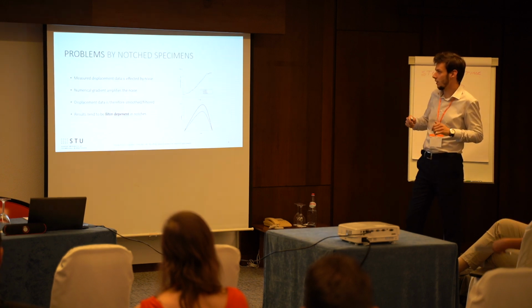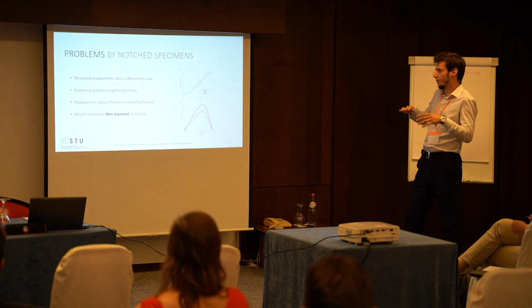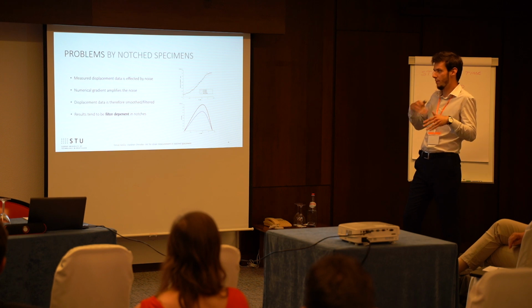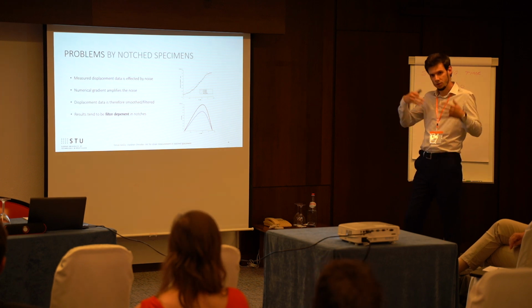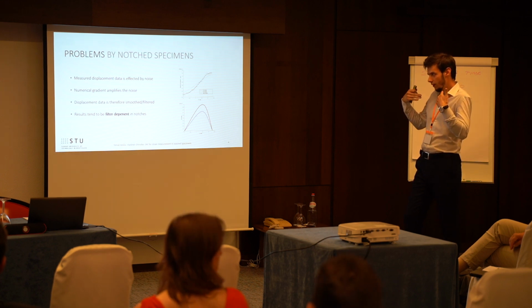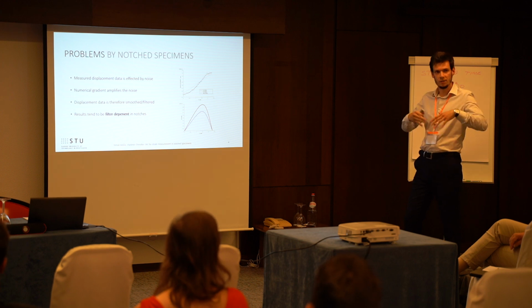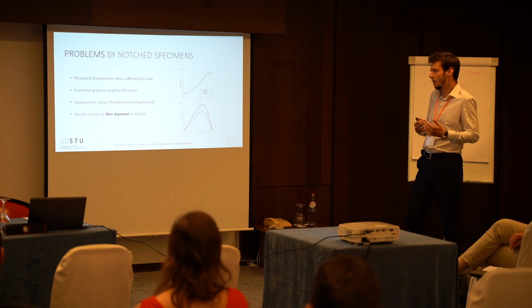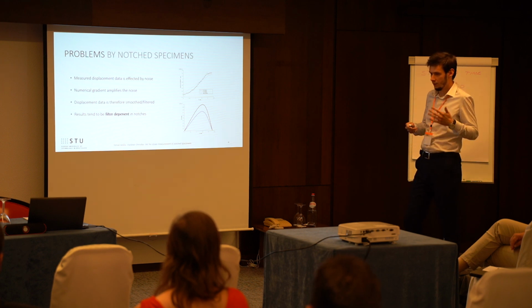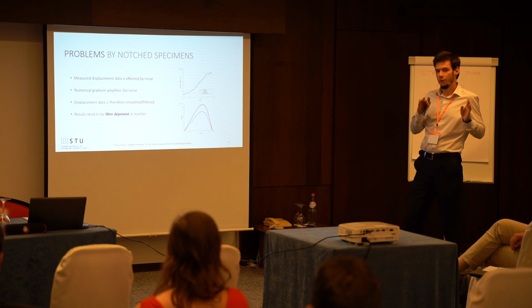Here comes a little bit of a problem, because the displacement data is most of the time affected by noise. When you calculate the numerical gradient to get the strain field, the noise in the data is always magnified. Therefore, most DIC systems use some kind of filter, smoothing algorithm or fitting algorithm.